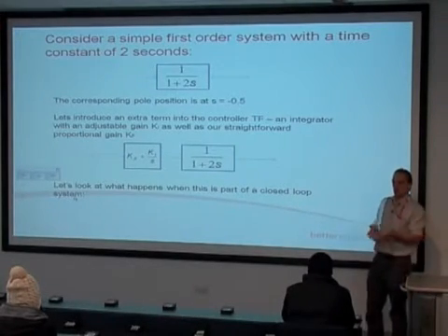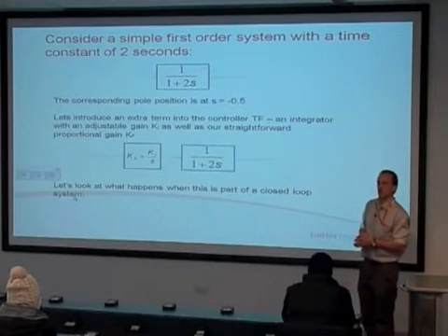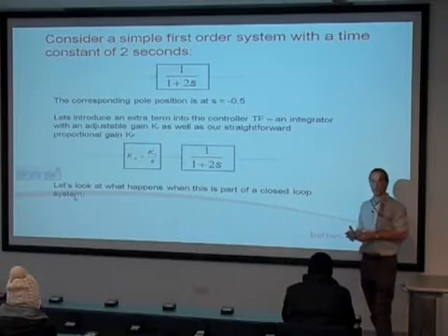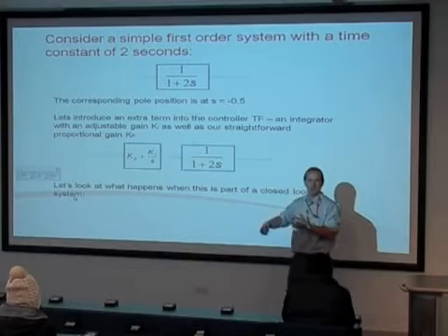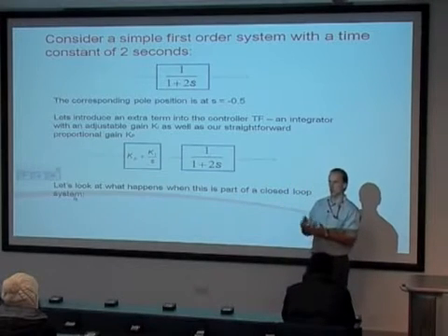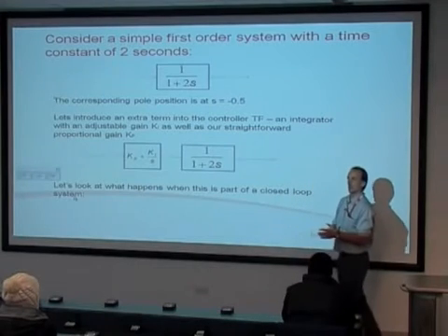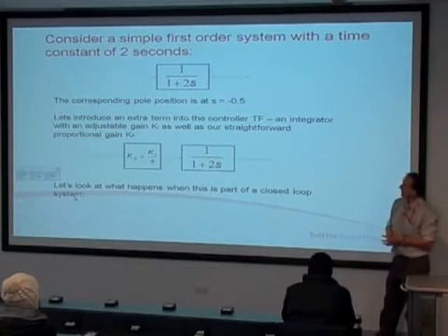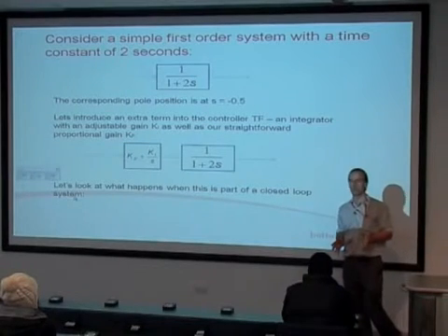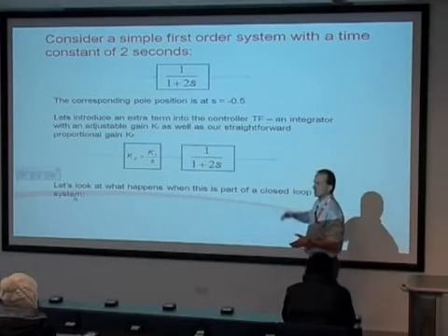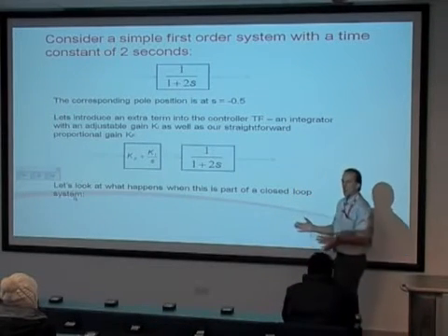And that's a fairly typical proportional only controller. Things that can happen with those, if you get it wrong, if you make K too big, is you can push the system into oscillation, and you end up going down the motorway varying in speed. Too fast, too slow, too fast, too slow. So in that situation, typically we wouldn't simply rely on the proportional control. We'd start to introduce some of these other terms. Okay, so that's the preamble.